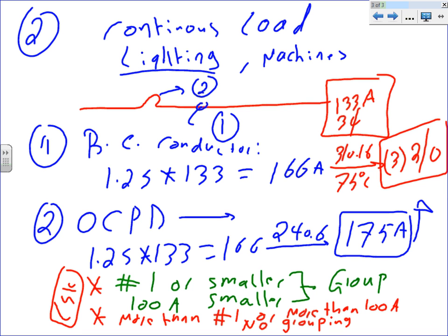Some people, guys, don't group even a 50 amp. If you have a 50 amp load, don't group it. Just give it a dedicated circuit. But these are the extremes. I picked the extreme. You really don't want to go and group anything higher than number 1. You don't. Even if you can, you don't. For voltage drop, for derating purposes, for multiple derating purposes.